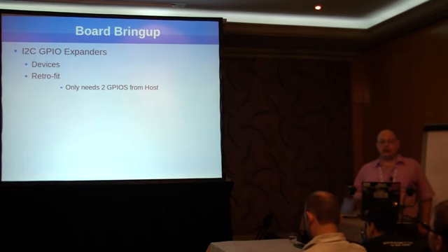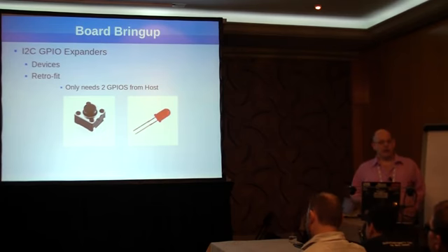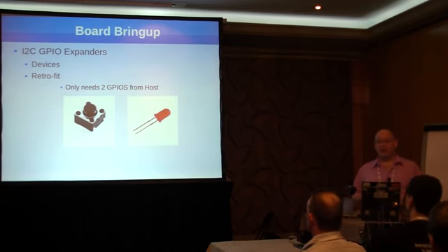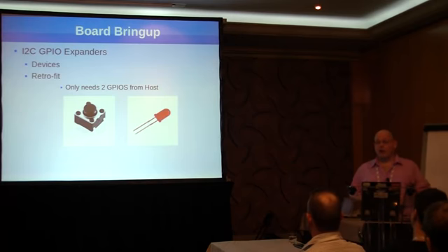You can usually take 2 GPIOs that you have existing on the design already and use the GPIO bit banging I2C driver as we discussed and actually set up an I2C controller that way. Where can you get 2 GPIOs? Most likely your board will either have a GPIO LED or a GPIO button somewhere on the design, and that's a pretty good estimate that you've got one of those 2 on the board. And you can actually steal the GPIO from one of those devices.